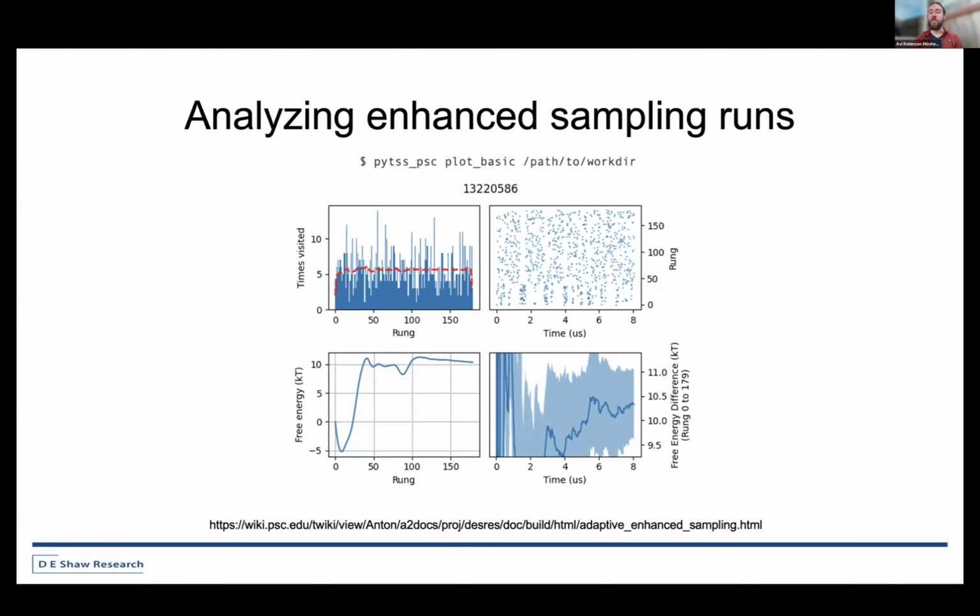If you run simulations and see a big discrepancy between the blue histogram and the red line, probably your simulation is not behaving well or hasn't yet sampled enough time. What you're seeing here is pretty acceptable. It's okay for it to be noisy. You just don't want all the histogram mass to be to the left, where the line should be flat.